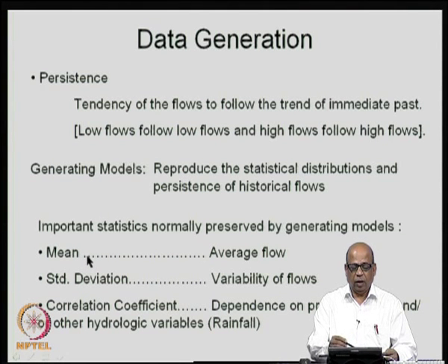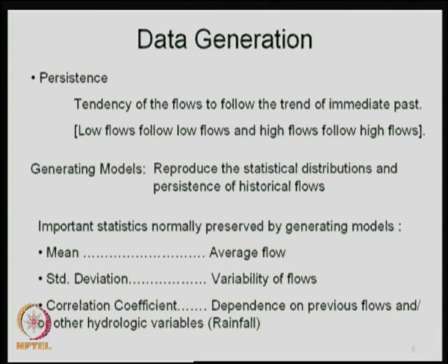have the same mean as the historical mean, or more or less the same mean. It will have nearly the same standard deviation as the historical standard deviation. It will have the same correlation coefficient as the historical correlation coefficient, and correlation coefficient we may talk about correlation between runoff and some other variables like rainfall, humidity, soil moisture and so on, or runoff at a particular time period with runoff at previous time periods.